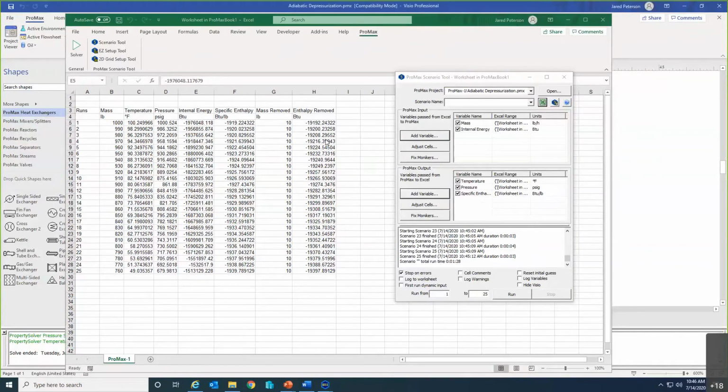We made a lot of simplifying assumptions initially. We said, all right, we don't have energy coming in, we don't have mass coming in, we're ignoring kinetic energy change, potential energy change, but there is nothing in that major governing equation that we had to throw out. We threw it out to simplify things. But if you have a depressurization case where these things are not ignored, it would be very easy to plug them in and do this exact step.